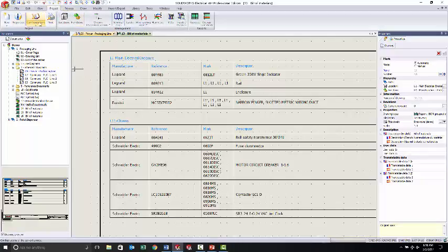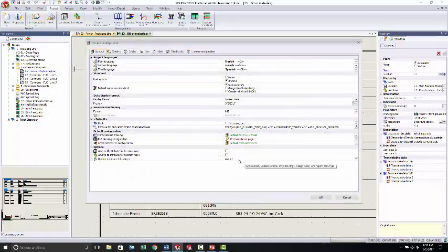There is a process here that you can actually do when you are setting up the project that now says right here, update generated drawings. Do you want to, whether it's ask me, never update, or always update? This is referring to whenever you close out this project. It is either going to always automatically update all the generated drawings for you, so you don't have to remember to hit the update button.